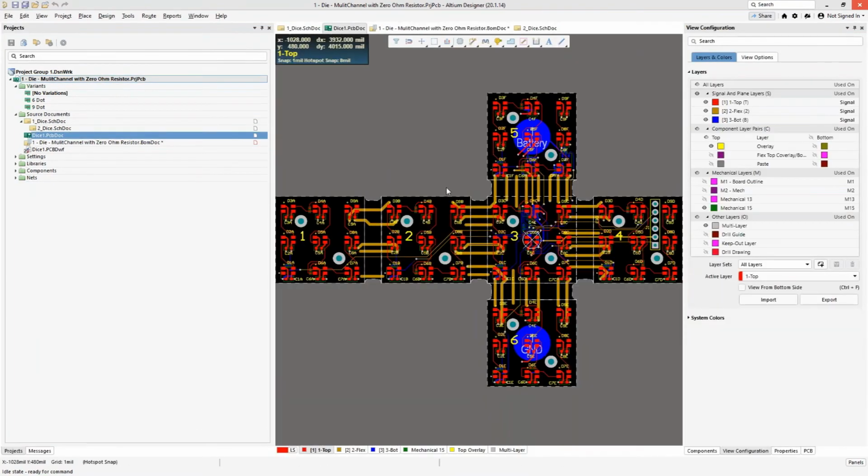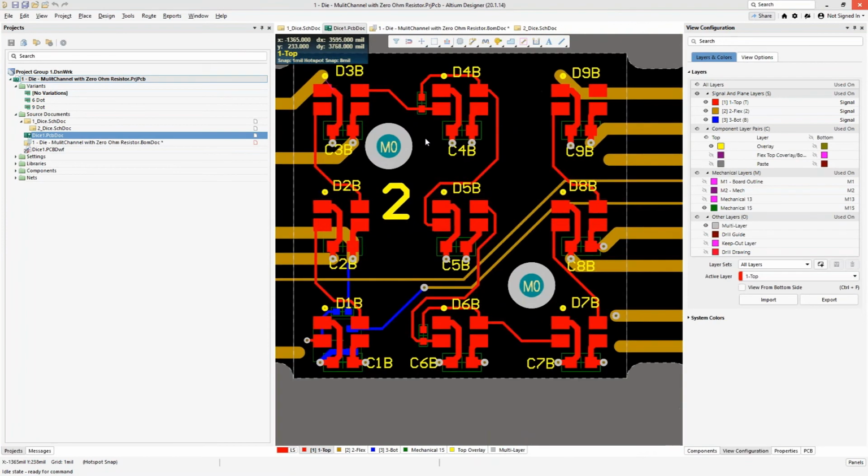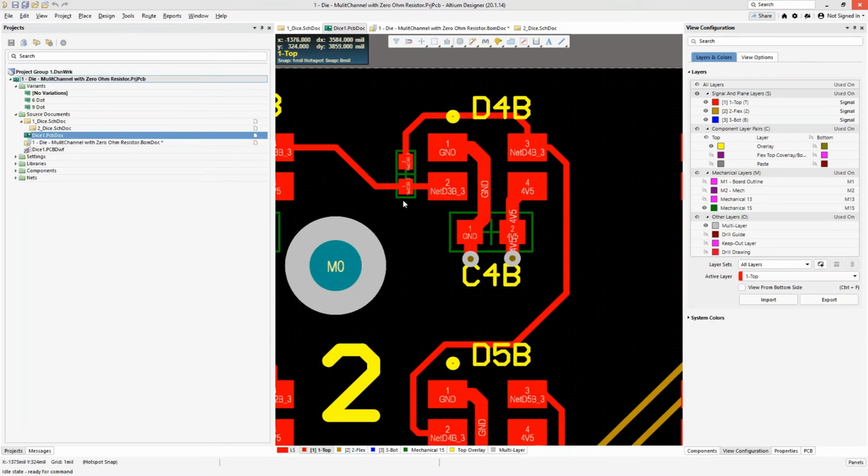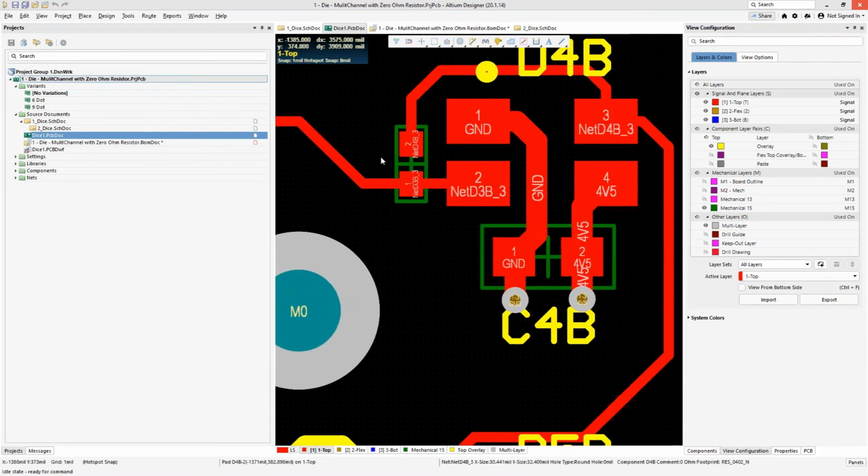At least we'll start off with those. And in particular on the PCB, this is what I had to do. I did all this because it took me a good hour to introduce the parts and to draw these out and to move a few things around so that I could strategically place this in. I do have an alternate part in here. Okay, and this is again a multi-channel device. I've done this on all of them, so I'm not trying to break any of the rules about having something on one multi-channel and not having another one. All 6 multi-channels have the same thing on your D4, D6, C4, and C6 components, but D4 in particular. What I did was I put a 0 ohm resistor in here. And so I had to put this in here and then I had to string it out.